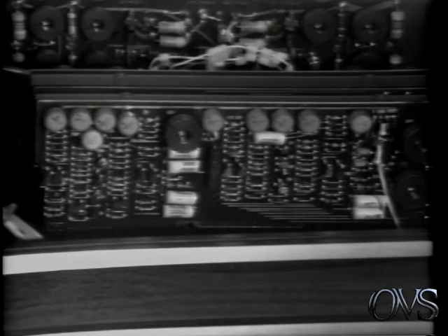Lastly, position the spot at center screen and adjust Y-axis astigmatism adjust number 2 and Y-axis focus adjust number 2 for best spot. This concludes our discussion on adjustments. All other adjustments are similar to those in standard oscilloscopes.